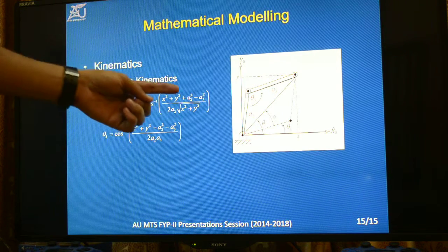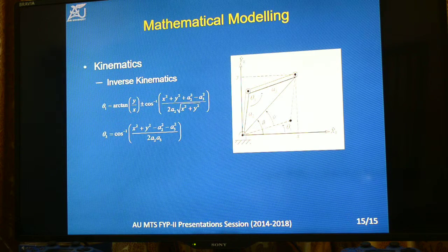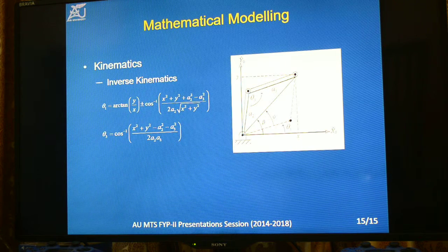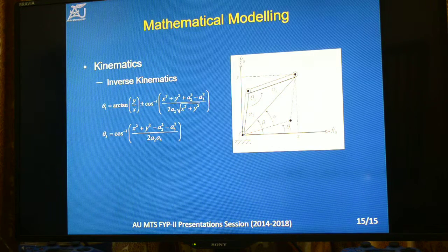This is the top view of our Netrunner 4-axis robot. The only angles that contribute in the motion of the end effector are theta 1 and theta 3. The prismatic joint is only making our robot go in the z direction. So finding theta 2 over here is of no importance because all of our revolute joints are revolving in the same axis. We use the law of cosines to find theta 1 and theta 3.